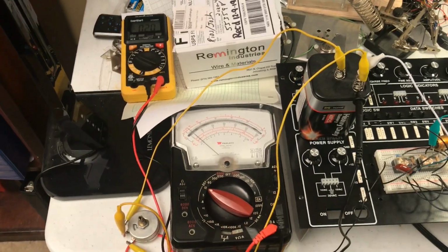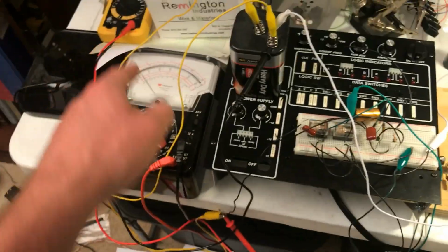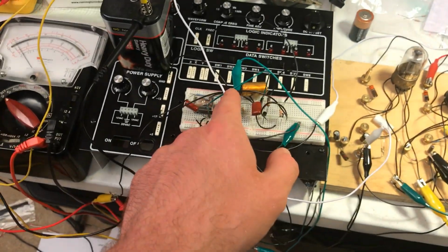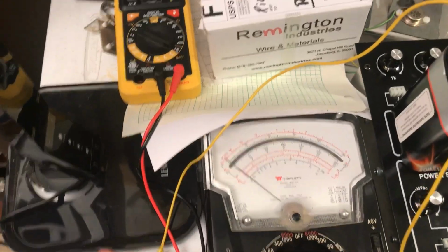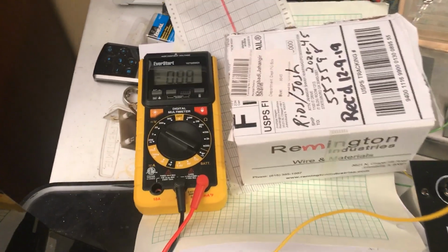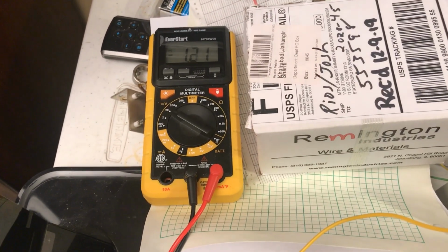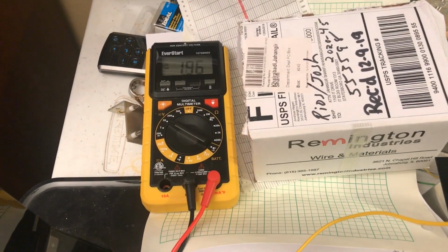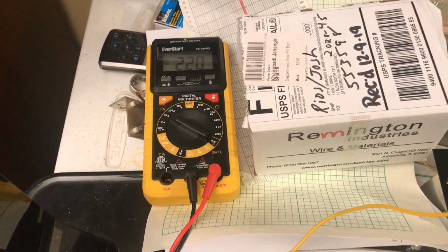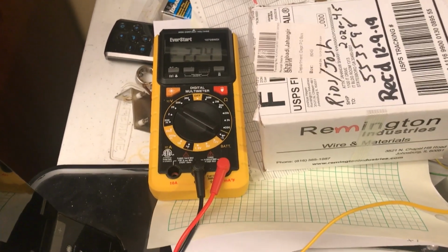It amplifies direct currents. And so it goes from DC to AC, amplify the AC, rectify the AC, back to DC with the feedback, and there you go. So I think this is a pretty interesting circuit. When you turn it to 0, it goes to 0. Let's see one more value. Let's say we had 3. Let's see if it'll give us 15. I think it will. My money's on it giving 15.